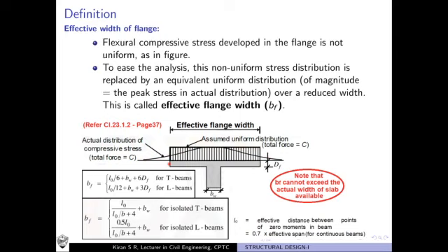But we are interested to find which extent of this slab is forming the part of this flanged beam. We don't know. So for which case we assume that there is some length over which the stress is applied in a uniform way. So there is a uniform distribution of compressive stress. We are assuming it. This is not the actual one.